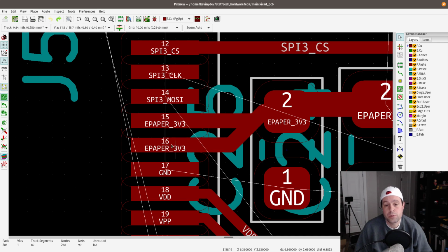There's different ways to approach this where I have taken the traces out. You can see I've used a much thicker trace here because it's a power. It doesn't need a lot of power, but I just used the thicker trace. You could just glob these together and make them one solid pad, but again, you have to think about what the solder profile is going to be and if that's going to cause issues when you're trying to reflow the part. So I think it's more best practice to have these come out and then join into a thicker trace later on.